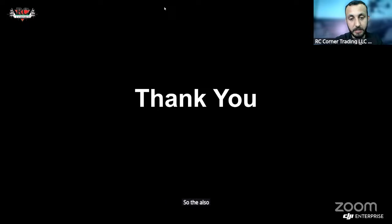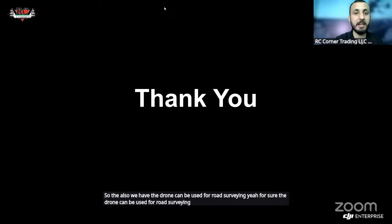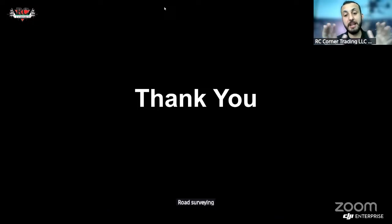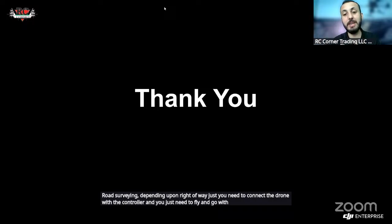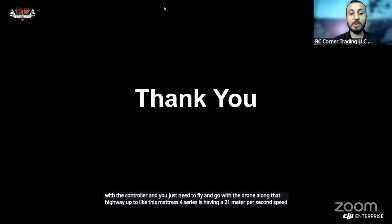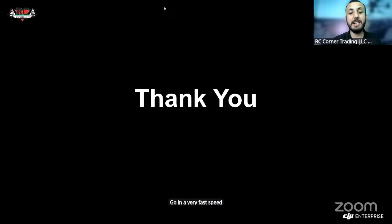Also, can the drone be used for road surveying? Yes, for sure. I have used it several times, surveying up to 1,000-kilometer highways. You can use it for road surveying depending upon the right of way. You just need to connect the drone with the controller and fly along that highway. The Matrice 4 series has a speed of 21 meters per second, so you can go very fast and collect your road data, and after that you can process it in a single way.